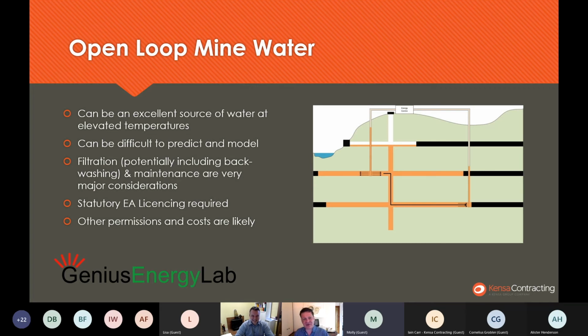I did a presentation on this a little while back, and I can redo that presentation and go into a little bit more detail on it. In summary, mine water can be very challenging to deal with. It's got, in the UK, very, very high iron content. That iron content will almost always come out of solution and will mean that you've got significant maintenance requirements. So whilst it's a fantastic resource and there's a lot of people out there promoting it at the moment, again, it's one to go into with your eyes open.